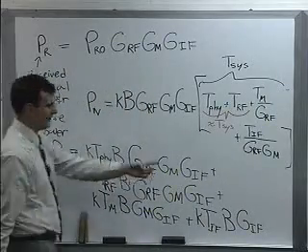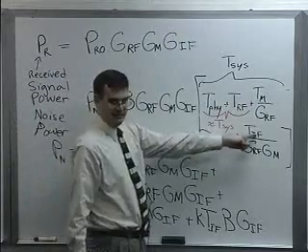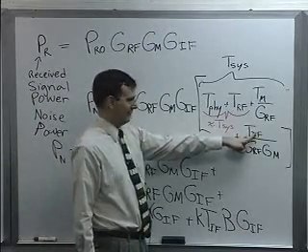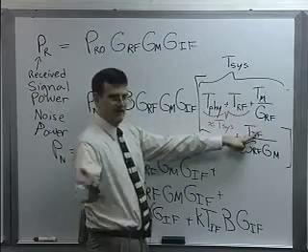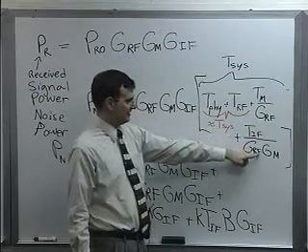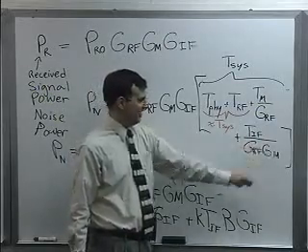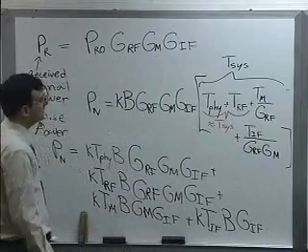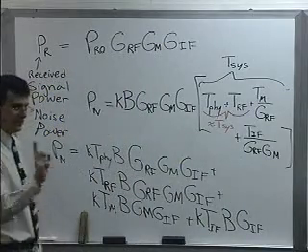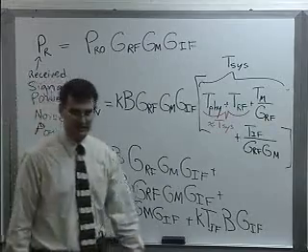That second amplifier down here, man, that could be a really high number. It could be 200 Kelvin, 500 Kelvin. Doesn't matter because it's getting killed by some of these gain terms in the denominator. So it's always that first component that's sort of the bottleneck in sensitivity.